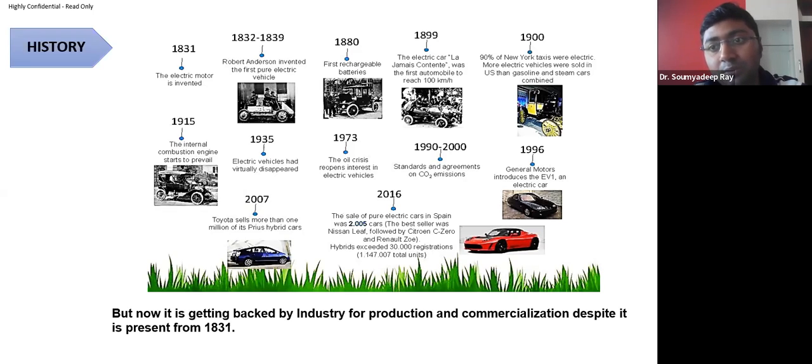But if the battery is able to take 80 ampere, then we call it 2C. If we charge the battery with 120 ampere and it is able to take it, that means 3C rate.